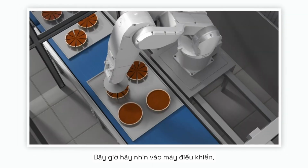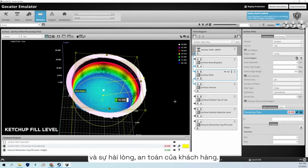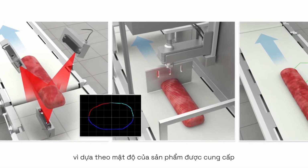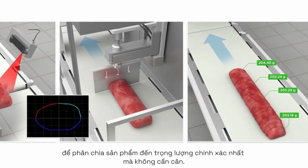Now let's look at machine control. A common example is container fill level, which is critical to product quality and customer satisfaction and safety. Another example is portioning of product based on volume. Since the density of the product is known, the volume measurement alone will provide the information necessary to portion the product to the exact weight needed.